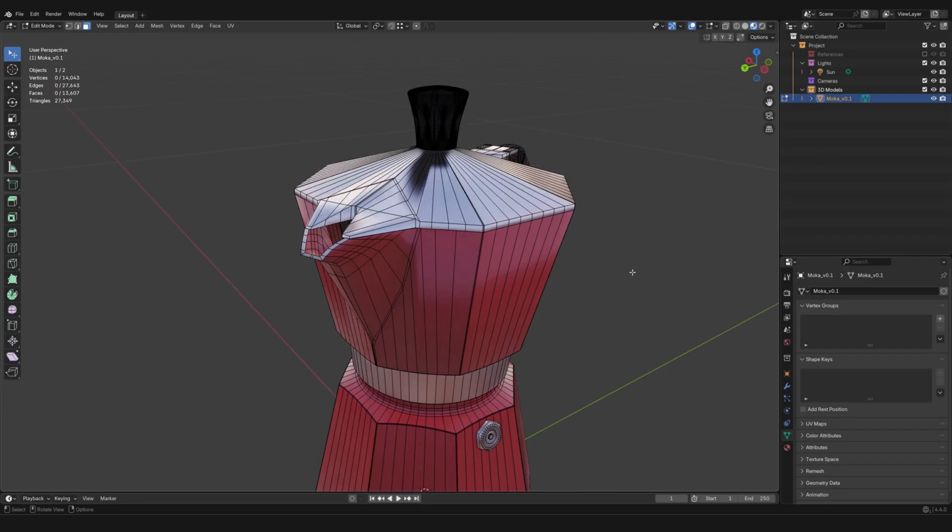Okay, so proportional editing. Proportional editing is your number one lifesaver when it comes to moving a lot of things together and reshaping or getting the rough shape and proportion of something in place. Like the name suggests, it allows you to edit things proportionally. And what that means is that, first of all, you need to be in edit mode to edit either vertices, edges, or faces. So right now I'm gonna press 2, for example, to go in edge selection mode.